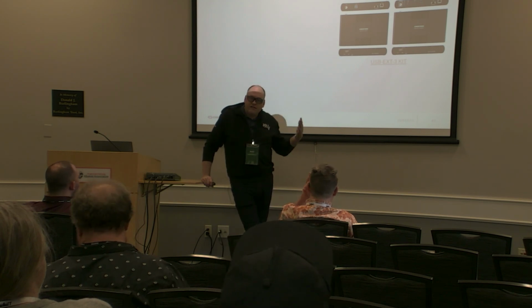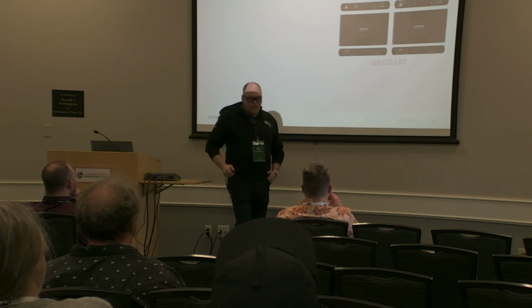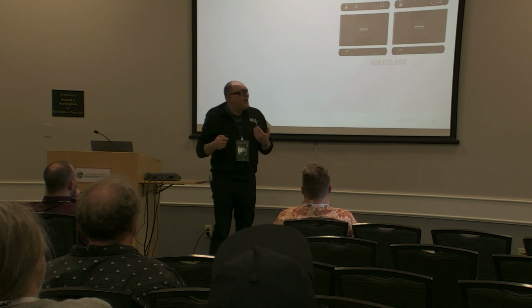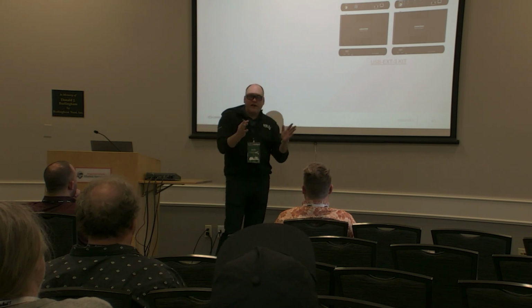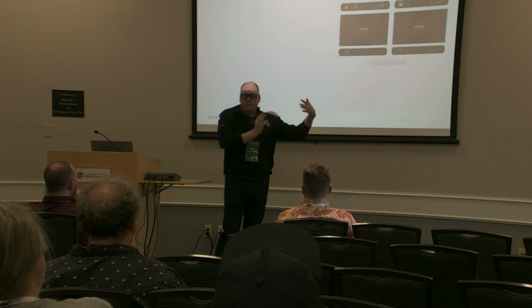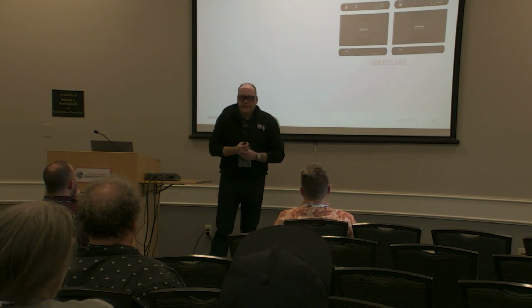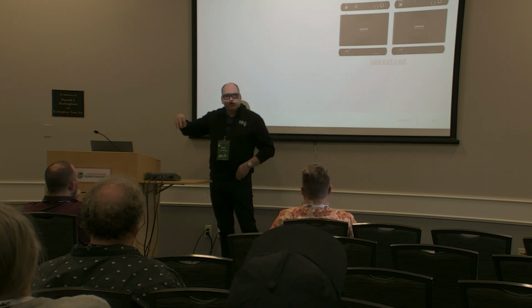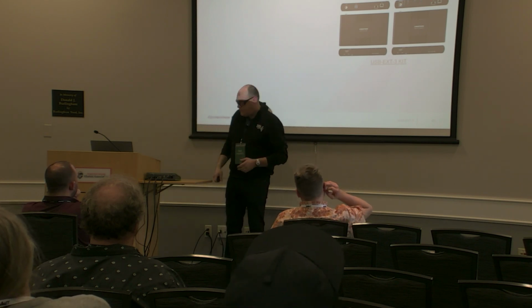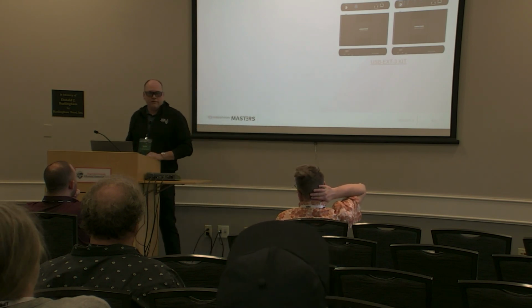Why does it do that? Because it's being reclocked. One of the questions that I had is, does the length of this cable and the length of this cable have to be less than the spec? And the answer is no. Each one can be the full spec, and that's because of reclocking. Pretty much every extender is going to do that, because it has to. Essentially, anytime you're touching a host controller, you're getting reclocked. And that's why it's interesting that our hybrid cable reclocks it without a host controller.